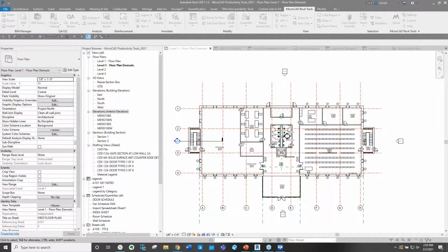Okay, hopefully that answers. And then another question back to Enscape actually, how much larger or does Enscape make the Revit files larger? The assets that we have, they're optimized for speed. So when you're placing an asset into the Revit drawing, it will add overhead. But the polygonal count that we offer is very low. So you can add a lot of assets without ballooning your Revit file.